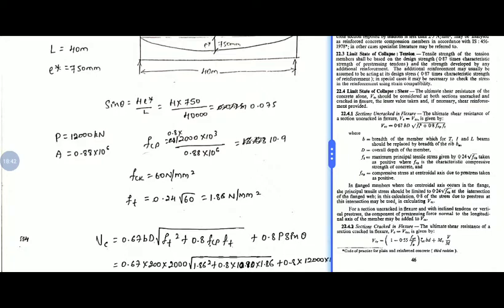So 80% of the vertical component of pre-stressing force you need to consider. Here directly the loss ratio is given. So loss ratio 0.8 into the vertical component of the PSC member. In the same page 46 you have this equation. You need to add 0.8 P sin theta.